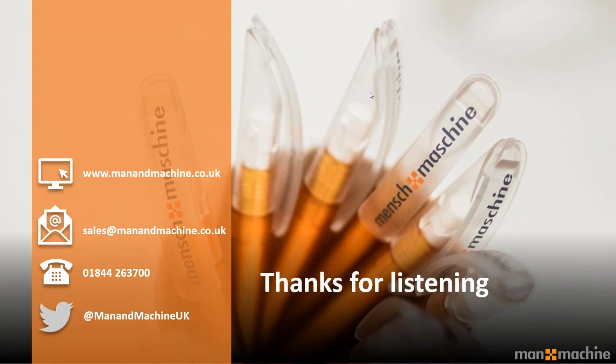So what is the added value of subtypes? It's a good question, Stephen. To be honest, it depends on what you're doing with the IFC on the other end. So if I was using Solibri, for example, and I was using that to have a custom classification, which is sorting out my objects and doing stuff with my objects, it would allow me to say, okay, go and find all of my ducts. Once I've got all of my ducts, go and say, what's a rigid duct?